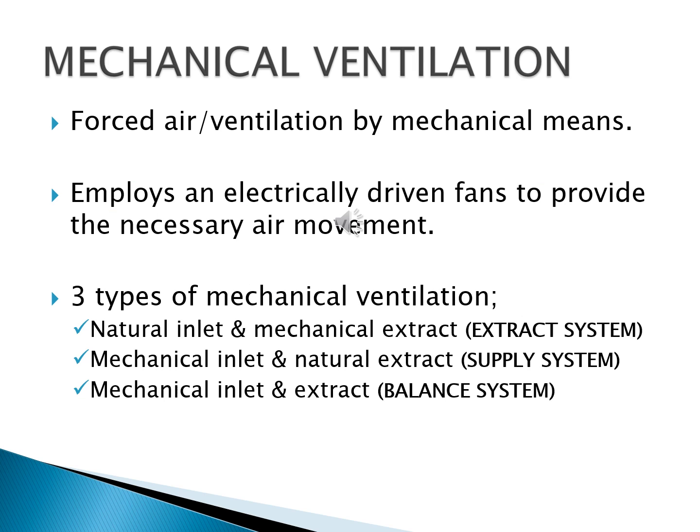Mechanical ventilation is defined as forced air or ventilation by mechanical means. It employs electrically driven fans to provide the necessary air movement. There are three types of mechanical ventilation: natural inlet and mechanical extract or extract system, mechanical inlet and natural extract or supply system, mechanical inlet and extract or balance system.